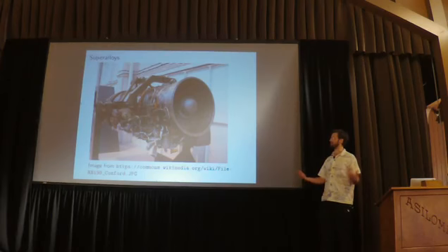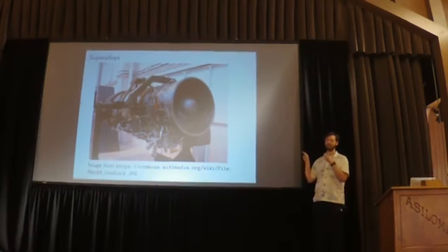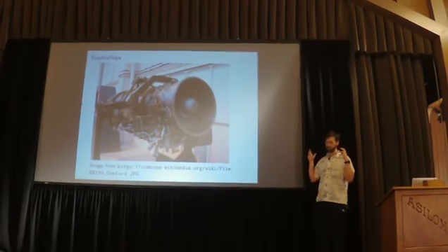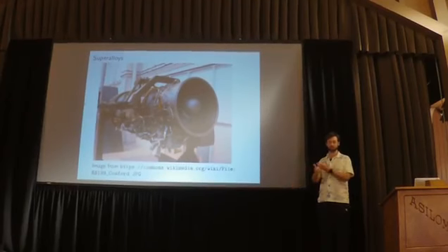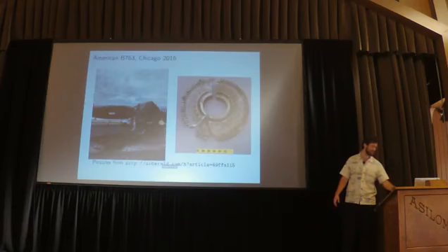And maybe that's sort of a sad goal to just be trying to make more money, but that's the honest truth of this. The downside to trying to operate a gas turbine at a higher temperature is that metals melt. Superalloys are metals. And if you operate it at too high of a temperature, your components will fail, and sometimes they will fail catastrophically.